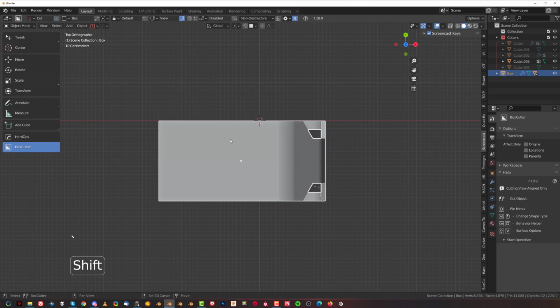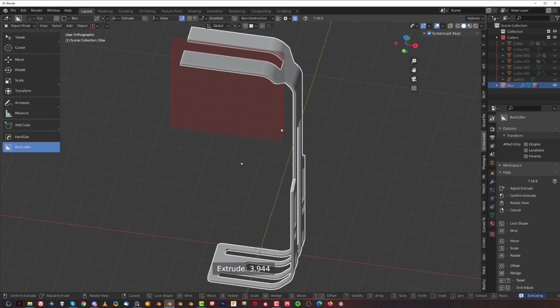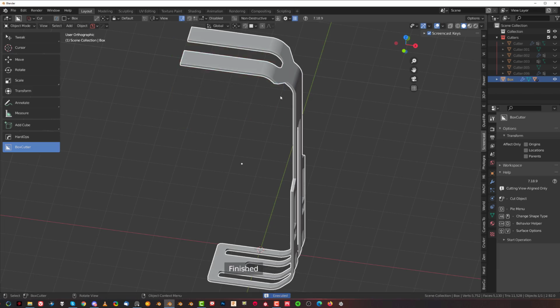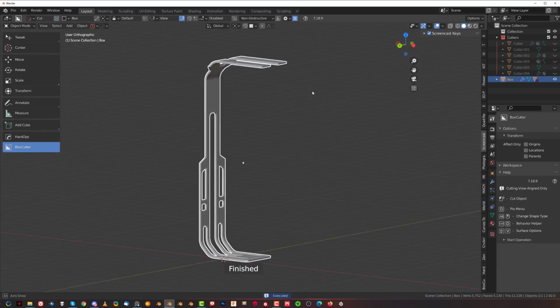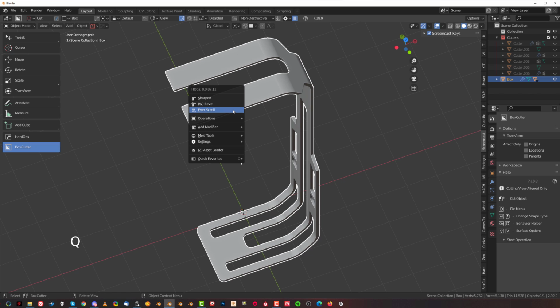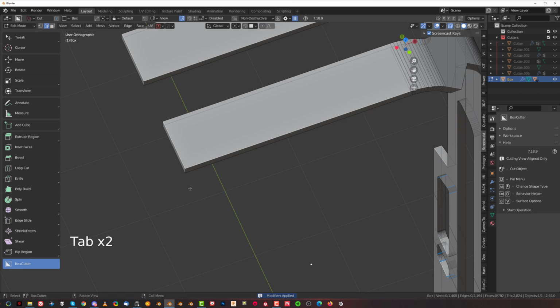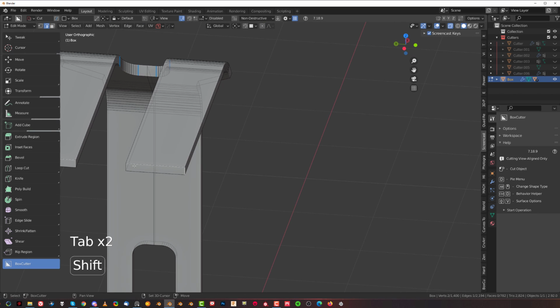Let's make this a bit lighter also. Let's make this look like there are two lights in here. So let's slice it in the middle here like this, right? Let's slice it, press B for bevel, because why the hell not? Okay, that's good. It starts looking like a light. And let's actually apply everything now. So let's go to operations and smart apply. Select these edges, right?